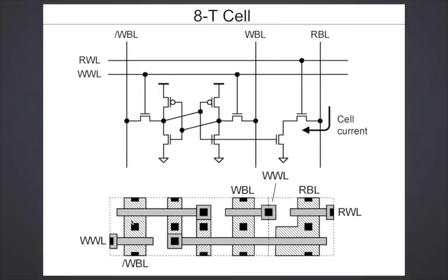In terms of budget, you are sharing the area, it's half. Similarly, the bit line contact is shared. This is the other inverter, just rotated and laid out. And so all the transistors are lying horizontal. So this is also good from the perspective of matching and so on. Same orientation improves matching of transistors.